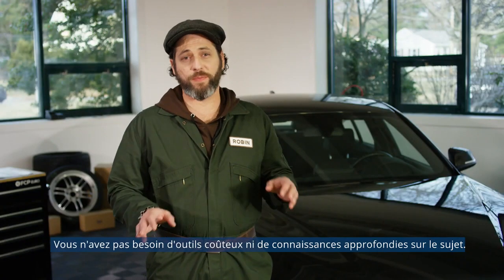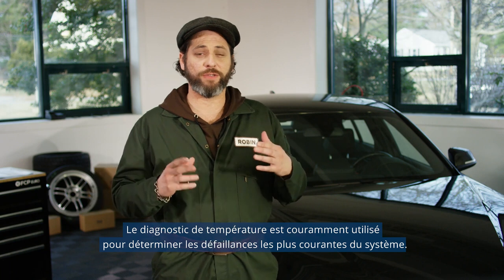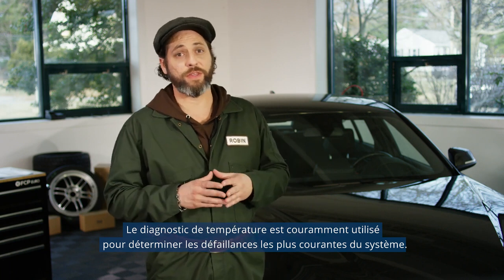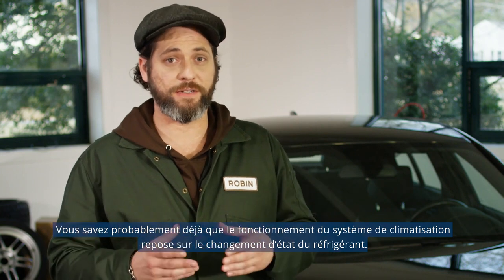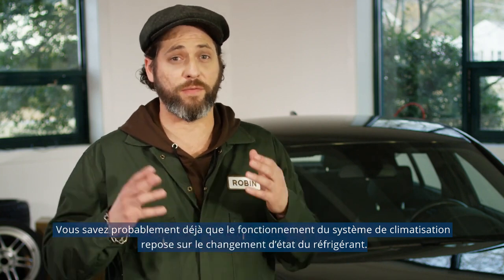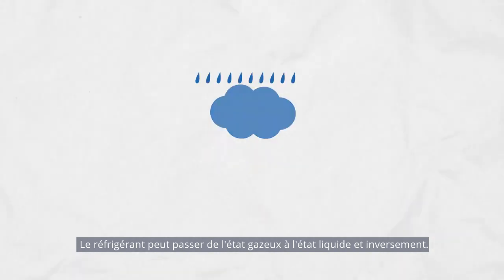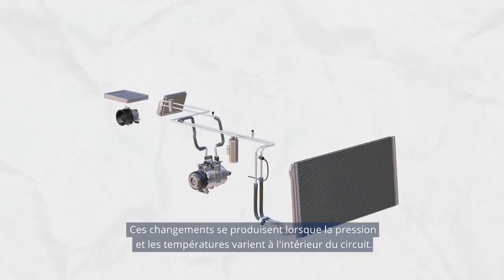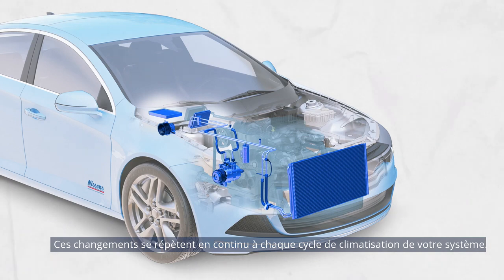Now, you don't need any expensive tools or a lot of knowledge on the topic. It's not rocket science. Temperature diagnostics is commonly used to determine the most typical failures within the system. Now, you probably already know that the operation of the air conditioning system depends on a cyclic change of the refrigerant state. The refrigerant can change its state from a gaseous state to a liquid form and the other way around. And these changes happen when the air pressure and the temperatures change inside of the loop. And these changes repeat continuously within every AC cycle in your system.